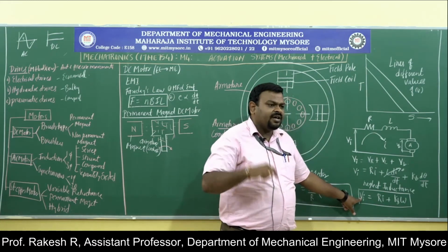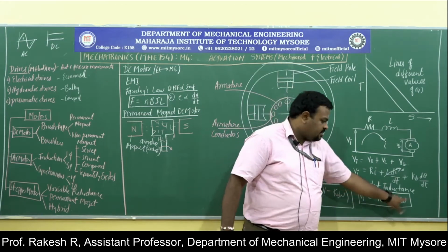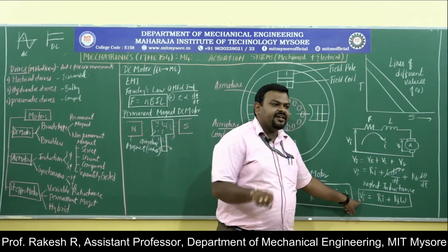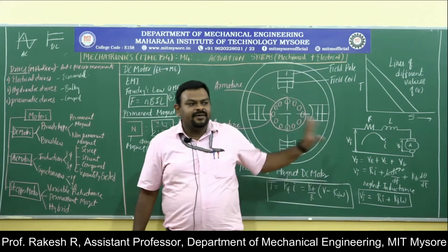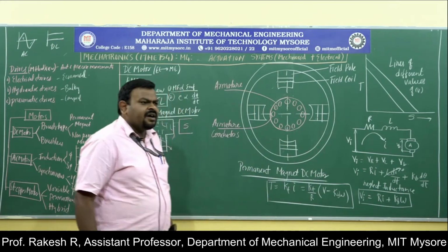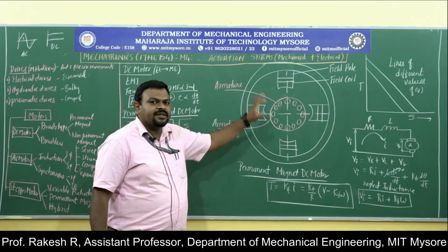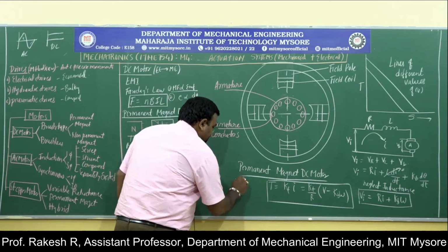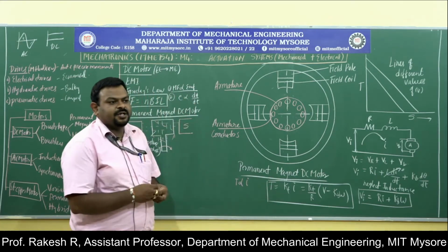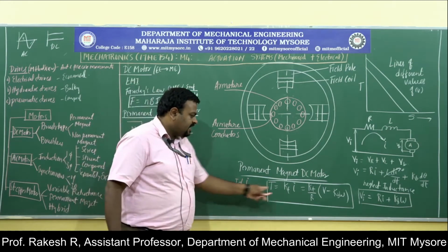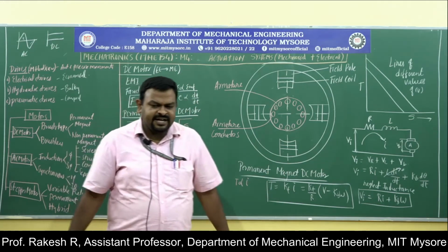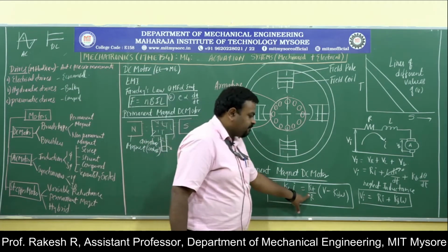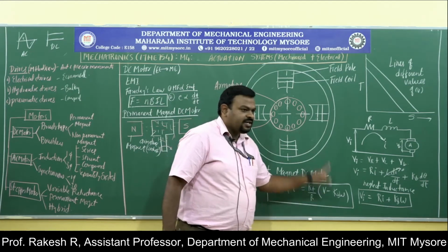This equation is proportional to current as well as back EMF. If there is no back EMF, then the voltage in the DC motor is directly proportional to the armature current. Also, there is a mechanical system here. The torque is directly proportional to current. If you take the proportionality constant outside, you get torque equal to K_t into i, where K_t is the constant of proportionality, called the torque constant. So this is the equation for the torque, and here the torque is proportional to voltage.